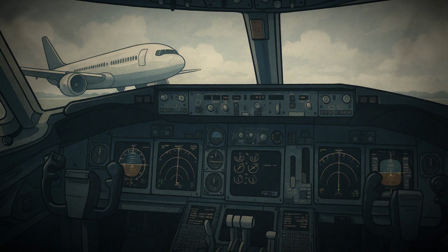While most commercial airliners cruise at speeds below the transonic region to avoid excessive wave drag, military jets and experimental aircraft must contend with it regularly. Engineers also consider additional sources of drag, such as cooling drag, caused by airflow required for engine cooling, and trim drag, which occurs when control surfaces are deflected to maintain balance. Even small components such as antennas, sensors, and landing gear doors can contribute to drag if not designed carefully.